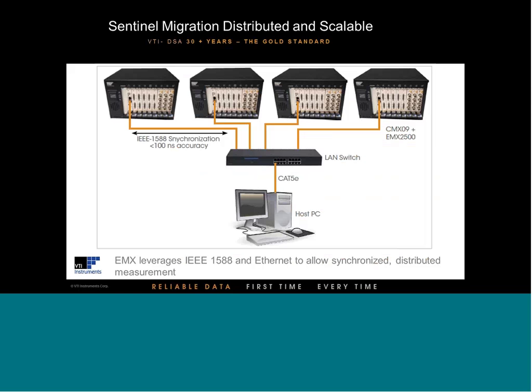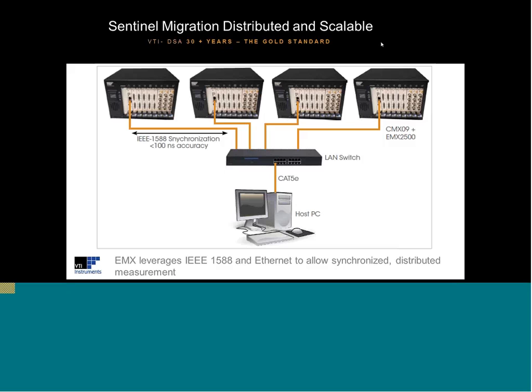The other thing that was key is we have a lot of users who want to be able to distribute the measurements. With the LXI standard that we leverage with this hardware, we have the ability to use IEEE 1588. The IEEE 1588 standard allows us to synchronize multiple measurements, not only noise and vibration measurements, but also data from other data sources. Here's a nice graphic where users can take multiple chassis and, just using a standard Ethernet hub, bring that back into a central computer, and they've got the ability to distribute each one of those chassis.